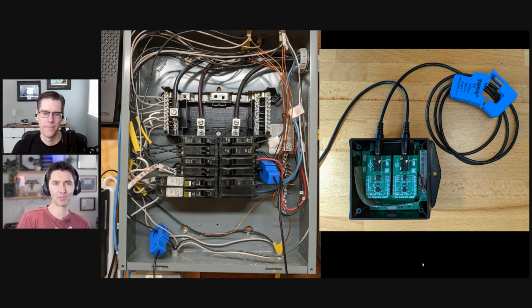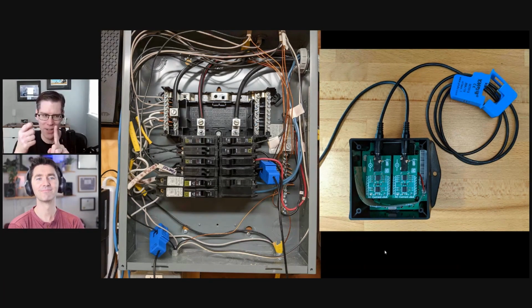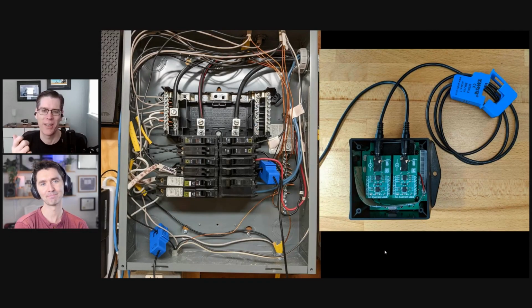You have AC current going through, creating a magnetic field around it. You can see power going through, but if you do it on both the hot and the neutral wire, it'll cancel out because current's going both directions then. Yeah, so for testing, I had a very carefully sliced extension cord that separated the two conductors from each other, still insulated, of course, so I could clamp around one of them.